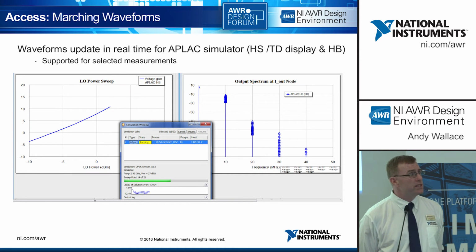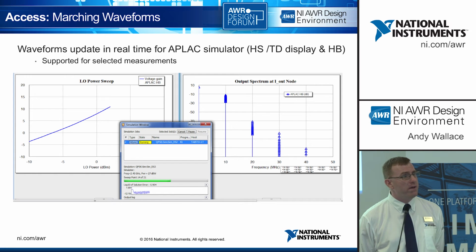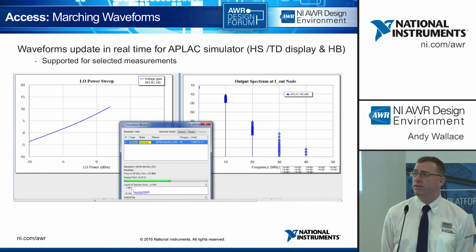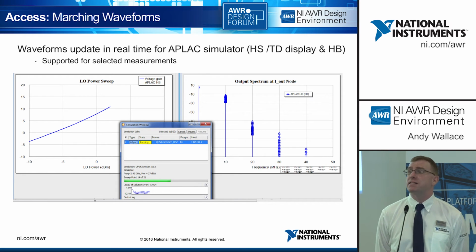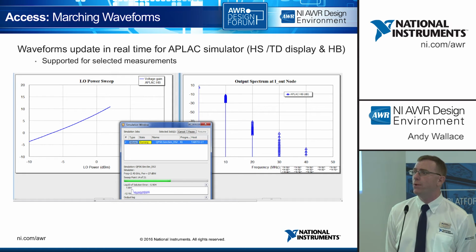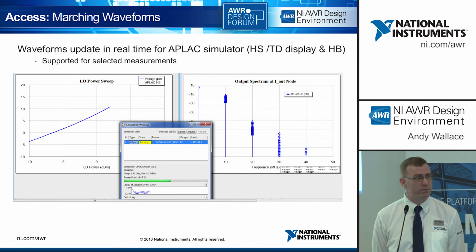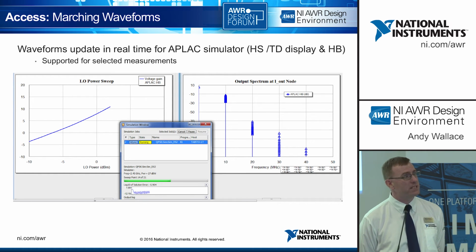Another improvement in version 13 is what we call matching waveforms. Now, I first thought of time domain simulation waveforms when I thought of that. So as time progresses, real time, you see the waveform appear. But we do the same with the harmonic balance engine as well. So if you have multiple frequency points, if you've got multiple power levels or test levels, you'll see those waveforms appear as time progresses. Quite often very beneficial.